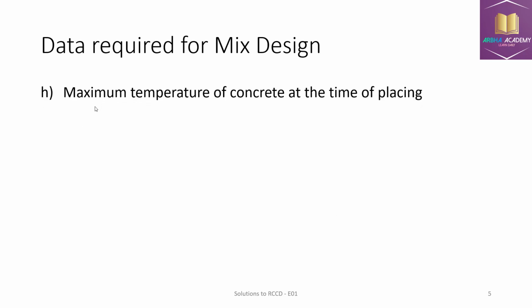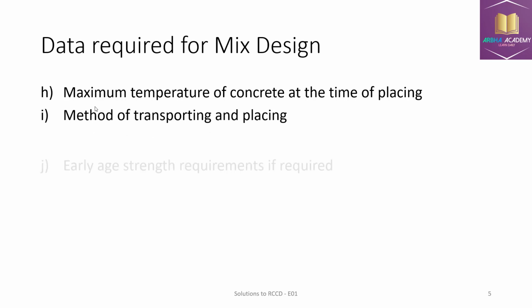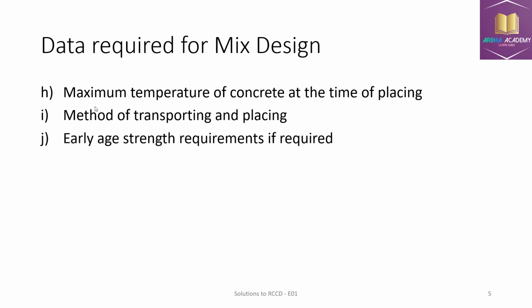Followed by the maximum temperature of the concrete at the time of placing. So there are multiple locations having different temperatures in the world. So at each location also the concrete is being poured. So depending on that, the placement temperature should also be taken into consideration. And the method of transportation, placing, as well as pumping. And then the early age strength requirements. For example, initial setting time in some situations needs to be attained in very few moments.